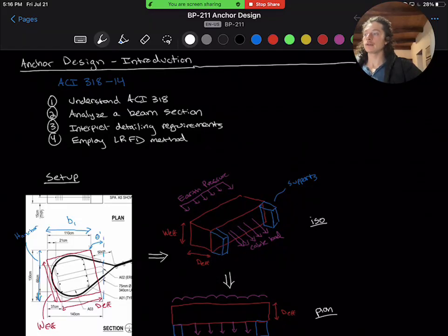In this unit, we'll discuss reinforced concrete design in the context of gravity anchors. The governing code for our analysis will be ACI 318-14, Building Code Requirements for Structural Concrete, which we will use to guide stability checks for flexural capacity, shear capacity, and bearing capacity, along with conformance to the requirements for the placing and detailing of reinforcement.